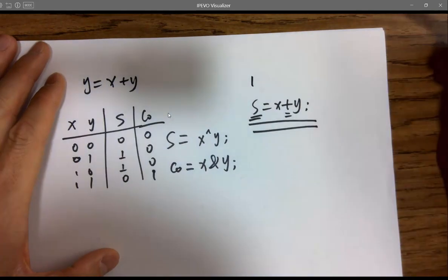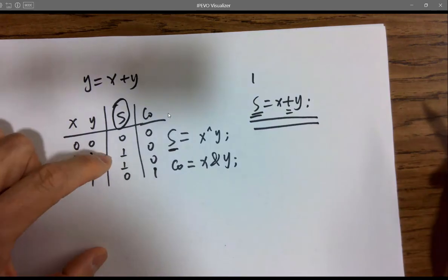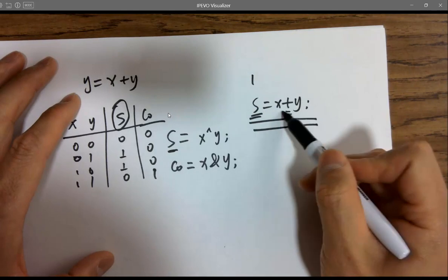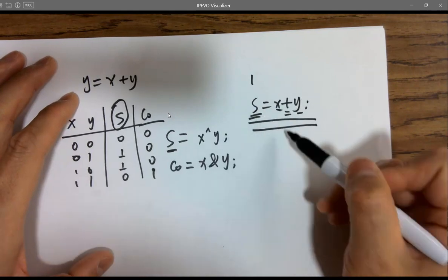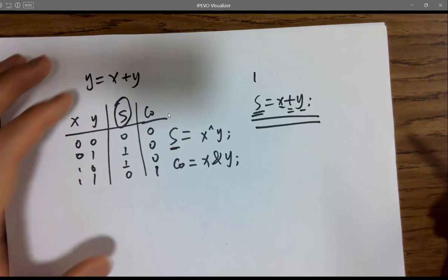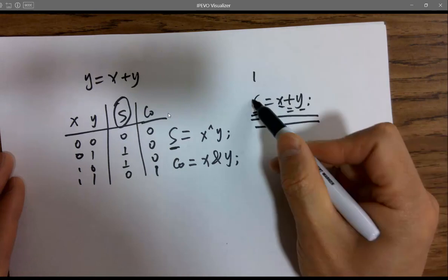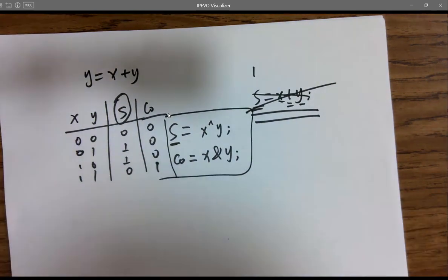I'm assuming a 1 bit. So for this s, how many bits are in this s? It's just 1 bit. So there's no way that you add 2 bits into 1 bit. Hardware-wise, it's not going to work. It's going to report an error. Even in C++ you can definitely do it, it's software. But here it's a hardware description language, so you cannot do that. You just have to always think about the digital circuit instead of programming when you are doing Verilog.